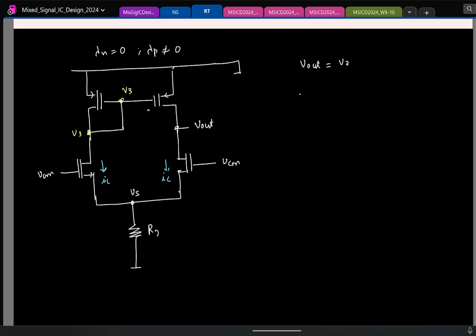So yeah, which means the moment you make this observation, we can actually simplify the calculation easily. So I know these two nodes are at the same potential. So what can I do? If you find two nodes having the same potential, what is the first thing that your mind tells you to do? I can basically short it. Nothing changes. So now you see that things have become nicely symmetric. So I can simplify the circuit like this.